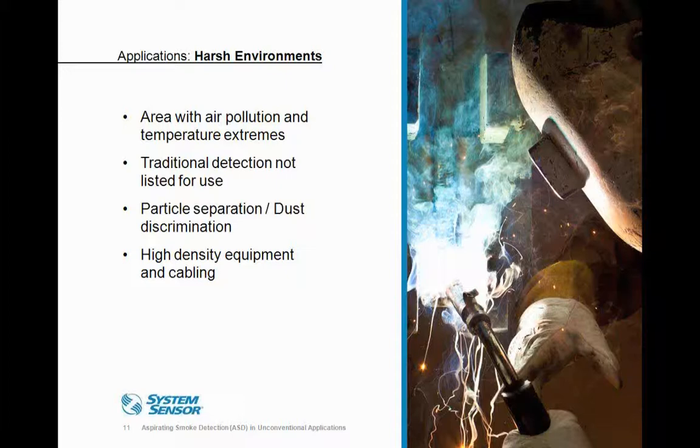So thinking of these dirty and dusty environments such as grain silos, cocoa processing plants, or even animal barns, many aspirating smoke detectors utilize various stages of filtration to eliminate nuisance particulate from the sample, which then maintains the device's sensitivity while reducing the occurrence of nuisance alarms. And Luis will talk more about how FAAST does filtration in a few more slides to give you some more examples there.